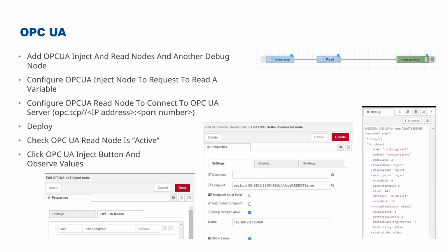Just a note on how we implement this, by the way. The way we implement these Node-RED flows is by using a web browser. So typically that would be on your development computer. You'd connect to your PACEdge device. You'd go to the PACEdge device's default IP address, and then that would give you a set of links which would then open up the individual applications.